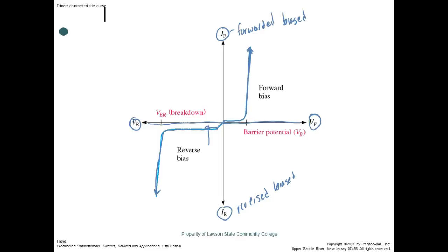Solid state devices can either open, or they can short, or they can become leaky, which is not good either way. So that means they would conduct a lot of current in the reverse direction. But anyway, we lose characteristic of the thing. So when you break it over in the reverse direction, then it's hard to say what the thing's going to do. Of course, if it shorts, you got a big problem, right? You understand that. If it becomes leaky, you probably got a fairly big problem because things are going to be getting the wrong polarity. Instead of get DC, it's going to get a little bit of negative AC or the other.